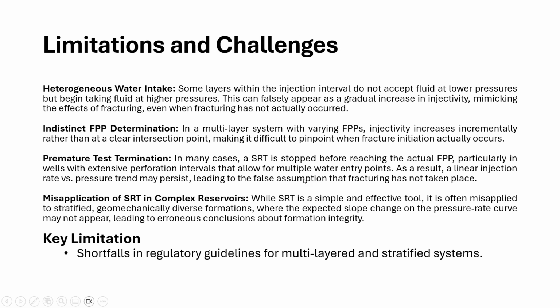So that being said, the key limitations and challenges that you face can be summed up here. Most importantly, heterogeneous water intake. Some layers within the injection interval do not accept fluid at lower pressures, but they begin taking fluid at higher pressures. This phenomenon can falsely appear as a gradual increase in injectivity, which means that it mimics the effects of a fracture, even though a fracture has not actually occurred.